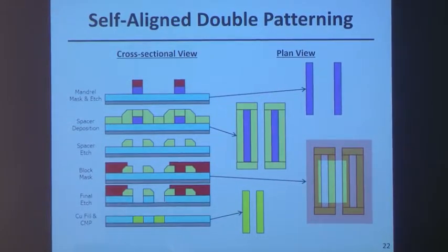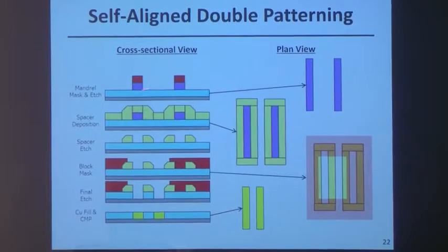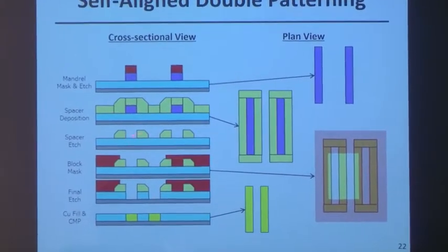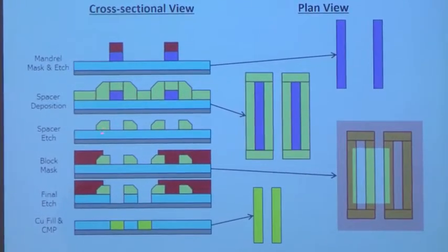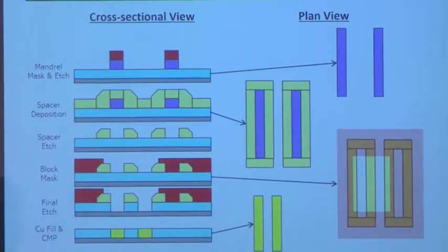So today, let's revisit the self-aligned double patterning. I showed how you can use the self-aligned double patterning technique to pattern 2 features for 1 lithographically defined feature. I just want to show here you can also use this technique to define 2 trenches, right? So let's say we use normal lithography to pattern the mandrel, the sacrificial material, deposit the spacer layer, and do an anisotropic etch to form the spacers. Then you can use a second mask like this to form the photoresist features here.